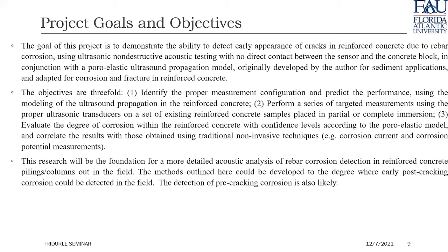Now, the goal is, again, to detect and demonstrate we can find early appearance of cracks and track it over time. The objectives are really threefold: to identify the proper measurement configuration and predict the performance, to perform a series of targeted measurements using the proper ultrasonic transducers, and to evaluate the degree of corrosion within the reinforced concrete.